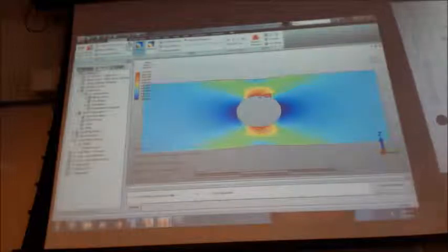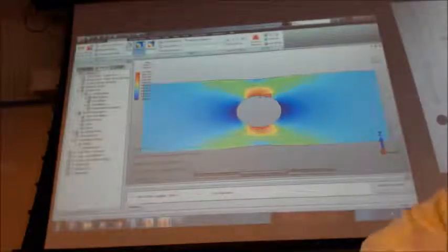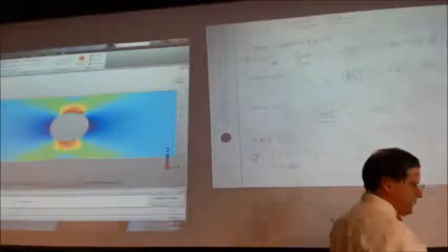So E-fatigue says 2.16, and by going to a mesh size of 0.06, it converges within 0.4%. So it does well.